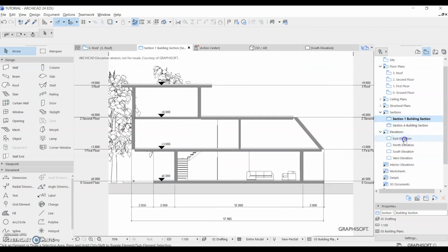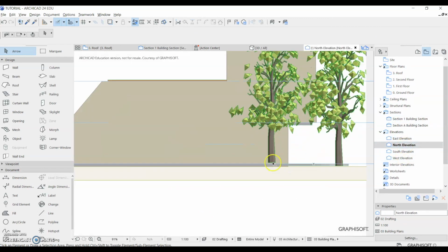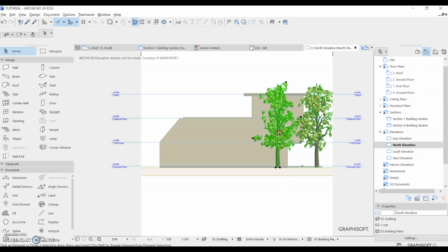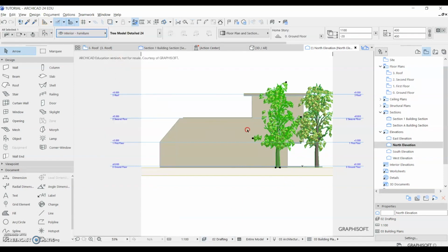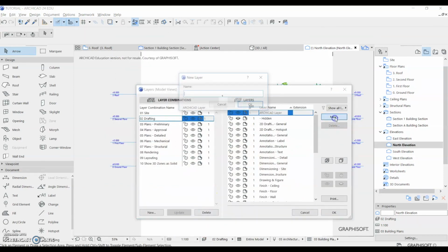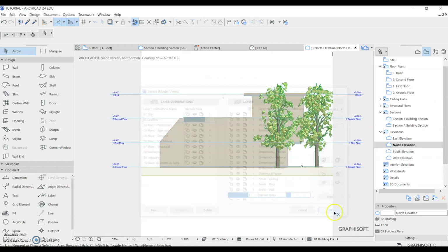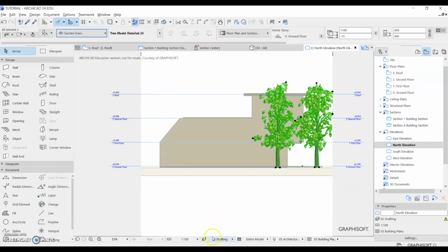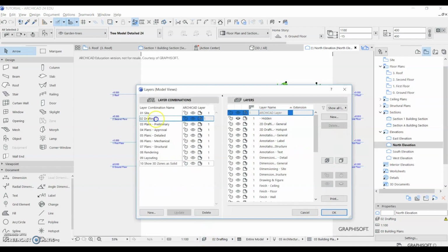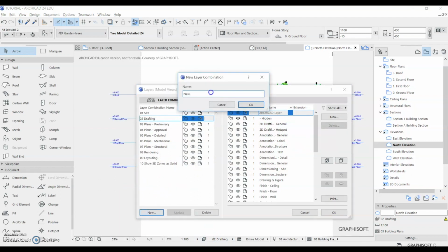So let's have a look at elevations. Trees are not exactly located on the floor, so I'm correcting those mistakes. We don't expect to see any objects that are obstructing our view. That's why I want to make these trees invisible on this elevation view map.